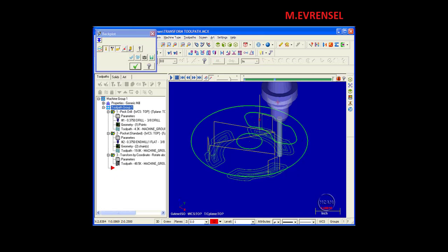So what ends up happening, my tool changer picks up the drill, comes through here, drills my entrance hole, puts it back, picks up my end mill and pockets, goes back, picks up my drill, drills this pocket, then picks the end mill up again and machines out the material in my two pockets. That's not very efficient to me.